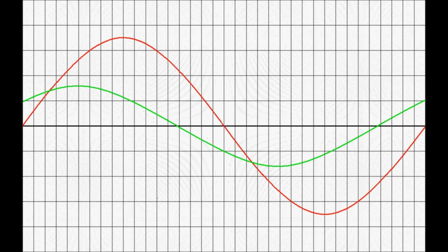It also doesn't demonstrate that an AC circuit acts exactly like a DC circuit at any moment in time, but it does calculate the opposition to current flow, the impedance in ohms, without any complex math. Just some simple algebra. We can also calculate the timing difference or phase angle between the source voltage and the current using a simple trigonometric function found on any scientific calculator. So let's look at those calculations.